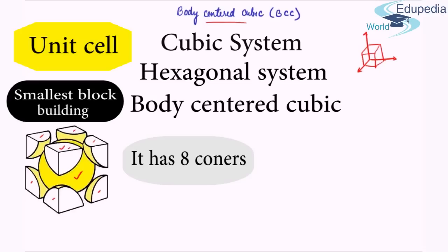So it's like 1 block here, 1 block here, 1 block here, and 1 block here, making 4 blocks surrounding this unit cell. Similar to these 4 blocks in this layer, there will be 4 unit blocks just on top of those individual blocks, right? So 1 on the right of the face here, 1 on the left of the face here, and 1 diagonal over here. So just a replication of this, 1 step on top of it. Thereby what we can say is that this atom is shared equally by 8 unit cells.